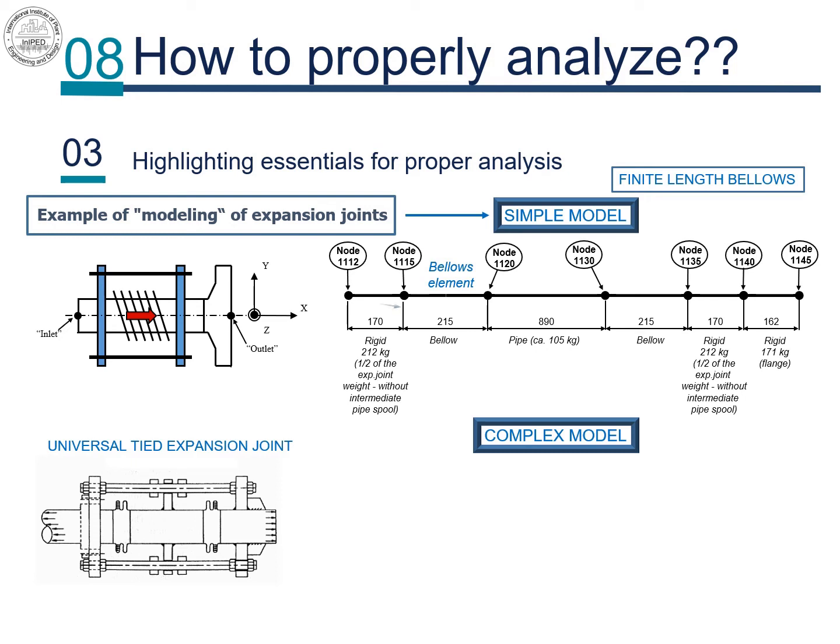Also, from node 1115 to 1119, where 1119 is a C node, a rigid weightless element is defined that is tied with node 1120, so that Y direction and Z direction translational movement is allowed, as well as torsional rotation, while all other movement between the node and a C node has been fully restrained.